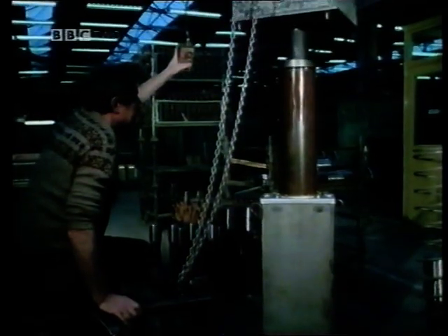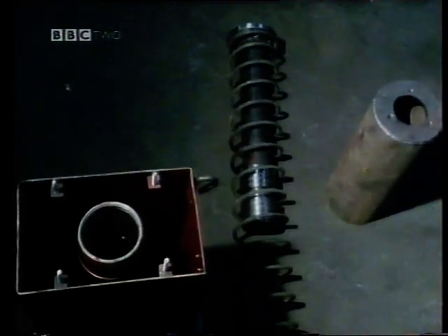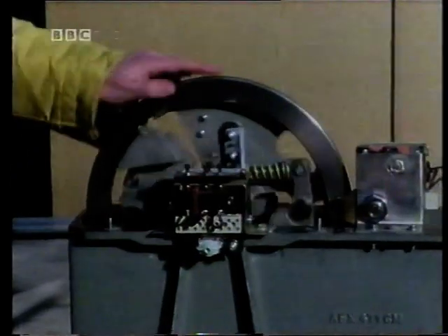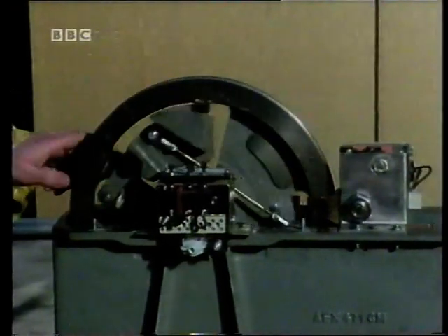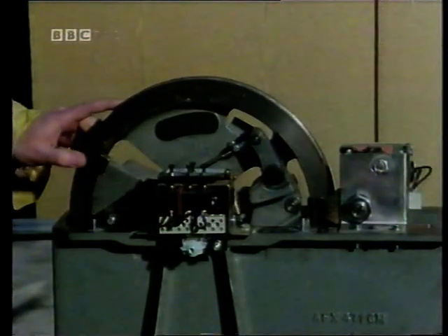The buffer itself, one's under test at assembly here, absorbs the car's kinetic energy by means of a hydraulically damped piston in compression. However, the buffer will only absorb kinetic energy at about normal running speed. Overspeed is monitored by a centrifugal governor. In principle, it's the same kind of device as used with the drum system.